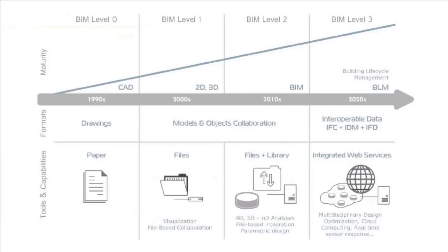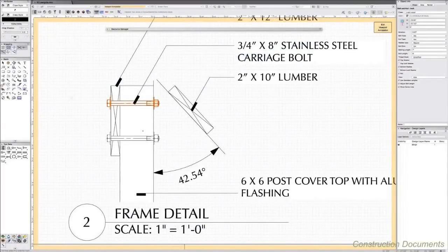The BIM workflow idea of doing details is that theoretically you've modeled everything and your detail is nothing but a section cut through a small portion of the detail you want to show, and you annotate that section cut so that if the model changes, the section changes and the detail updates along with it. Now that's the ideal in a BIM, but as I mentioned, I'm not going to do that for an irrigation head detail or a concrete paving detail.